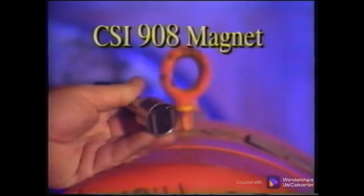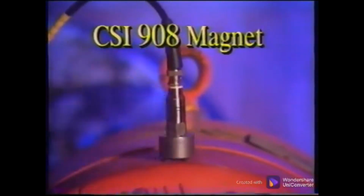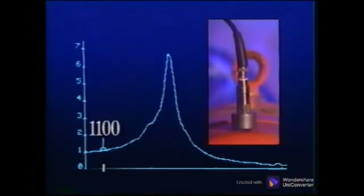This magnet has a powerful grip and 2 bevel bars or poles that will fit well on most flat or rounded surfaces. Using this magnet increases the linear frequencies of the same accelerometer to 1,100 Hz. Therefore, it can be used acceptably on shaft speeds to 3,600 or 5,000 RPM and acquire the data you need.